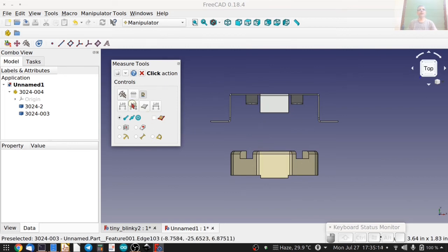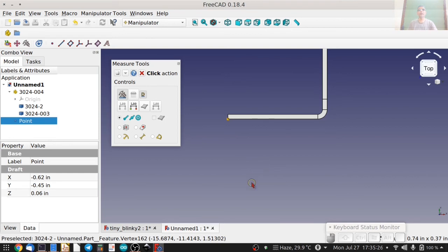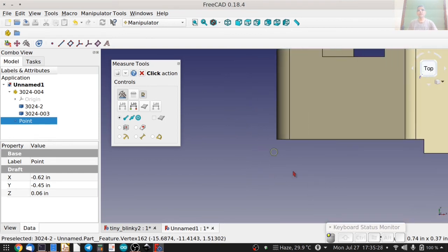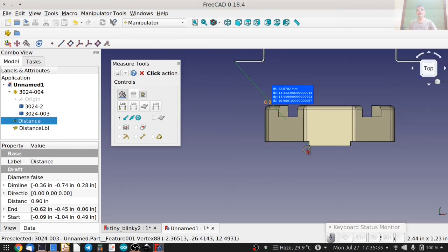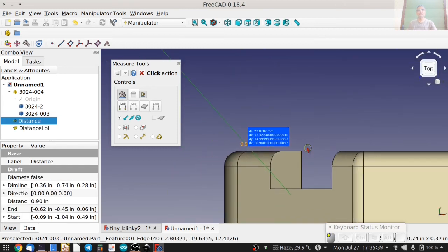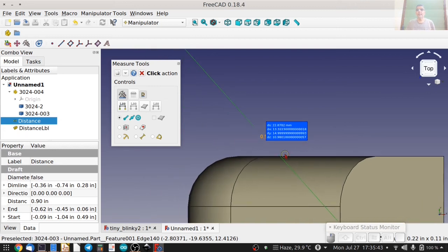So let's click on the measure button once, zoom in so you can grab a corner of this metal retainer clip like so, then scroll until you can grab this corner point, and if you look at the values now, we can see that in the y direction, the offset is, let's round it off to 15 mm.